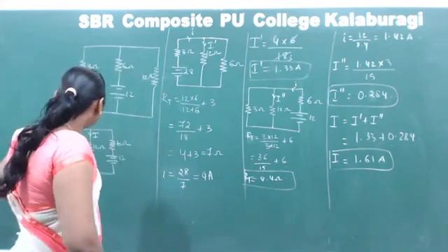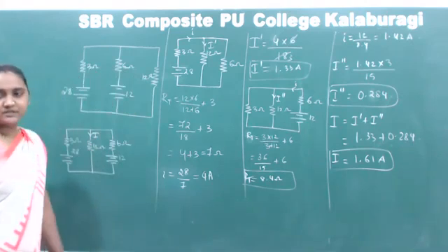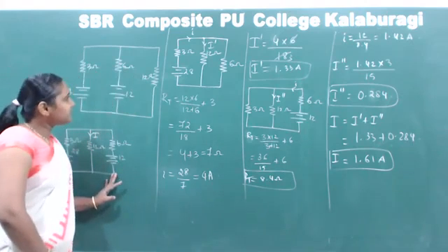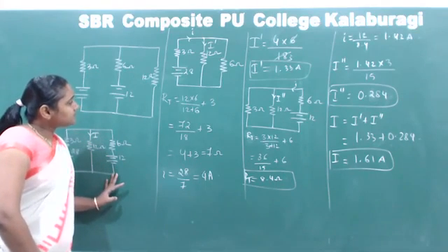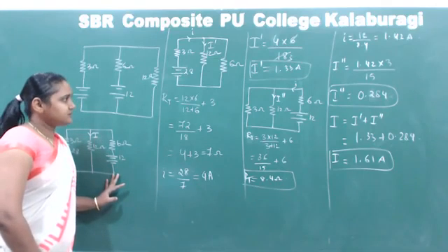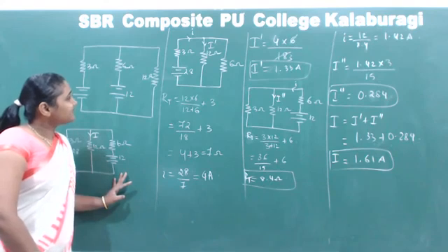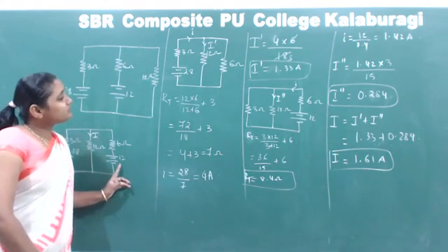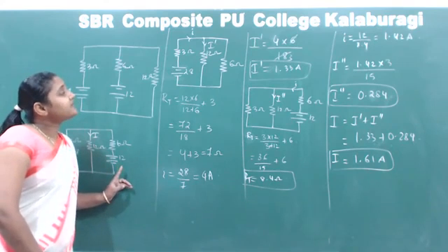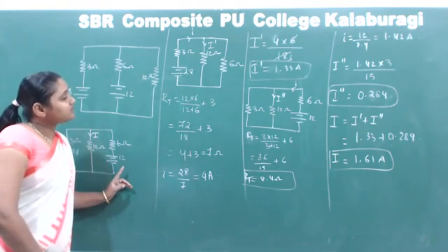So what we have to do here, first of all, I have just rearranged the circuit in this form so that we can easily draw the further circuits and we can make the calculations easier. Right? Next, after drawing that circuit, we have replaced the 12 volts voltage source there by a short, and we got the circuit like this.